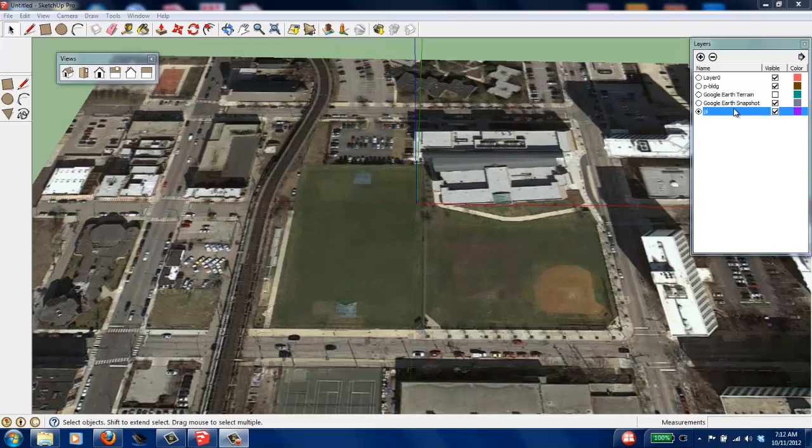Okay, I've got my property line layer current. I'm ready to draw in my boundary. There's a couple of ways you can do that. You can just draw a rectangle and eyeball it, but the proper way to do it is to key in the actual dimensions. I'm going to pick that first corner, and instead of picking my other corner, I'm going to type in the values of the dimensions, and that's 250 feet, comma, 375 feet.